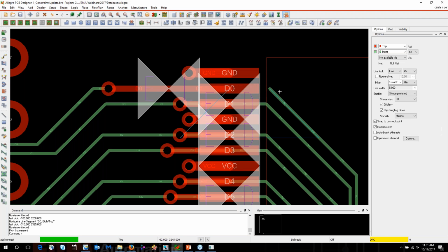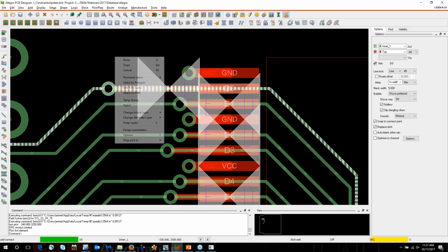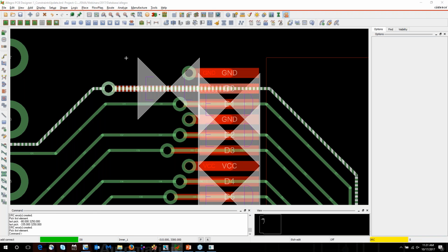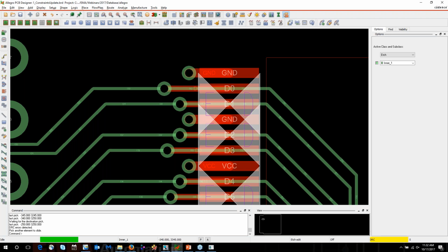Okay, let's go ahead and route this directly through to this via, where we removed one via. Now we still have another error here, and this is our maximum exposed length. It's supposed to be no more than 200 mils, and it's 260 right now. We actually shortened it some by getting rid of that other via. But let's go ahead and use the slide command and move the via over. Okay, so we got rid of that problem.